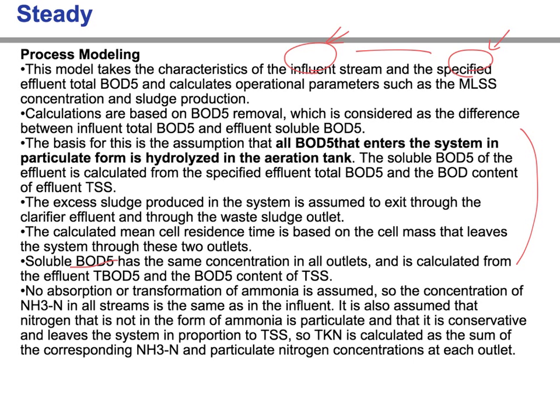And then let's talk about nitrogen. No absorption or transformation of ammonia is assumed. So the concentration of NH3-N in all streams is the same as the influent.